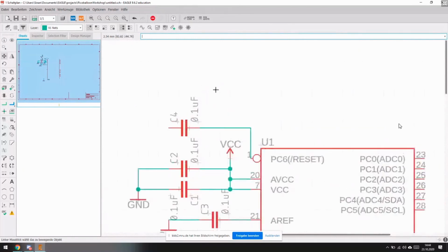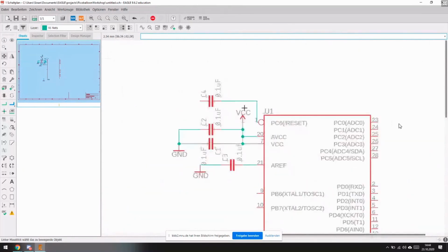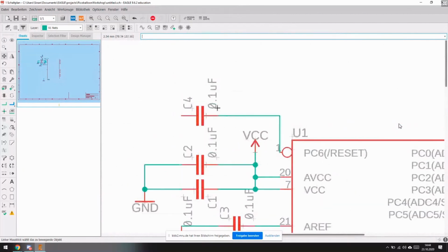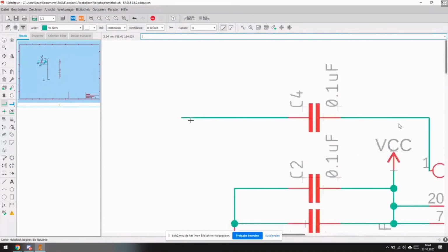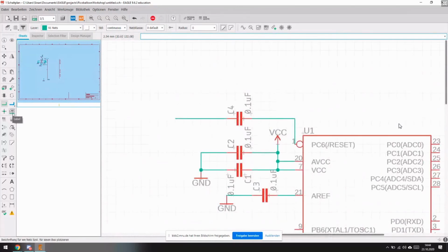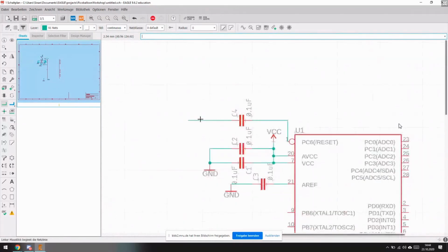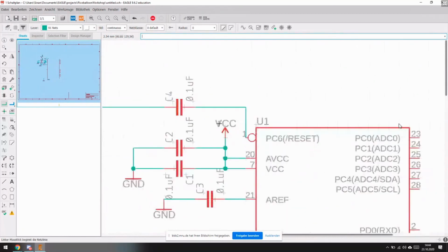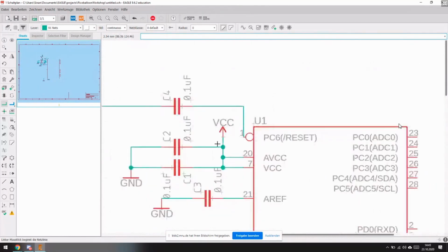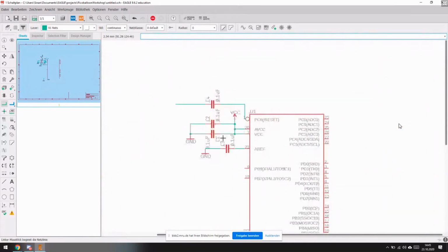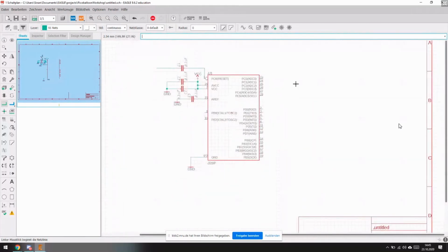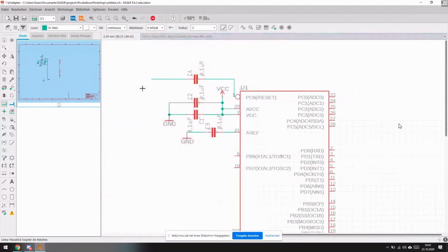Okay. So the thing is, we not only have pins and nets, we also have labels. If I pull out a net here, press escape, so I just drew the net, we can do labels here. Labels are like these VCC components here. They specify a specific net, and labels are especially important if you have big circuits where you have much stuff connected and you don't want 1,000 traces or wires to cross each other. That's when nets come in handy.